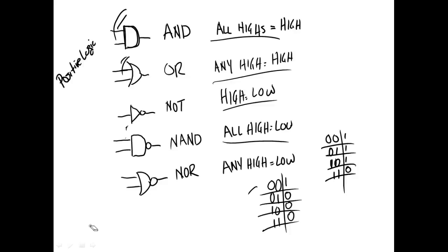But not only is it going to have the gates, it's also going to give you the Boolean equation for the gate, and also it'll give you no truth tables. Because if you understand this, this applies to all versions of this gate, whether it's 2 input or whether it's 10 input, right? You understand? Couldn't you imagine making a truth table for a 10 input OR gate? It would have 1,024 combinations in there.